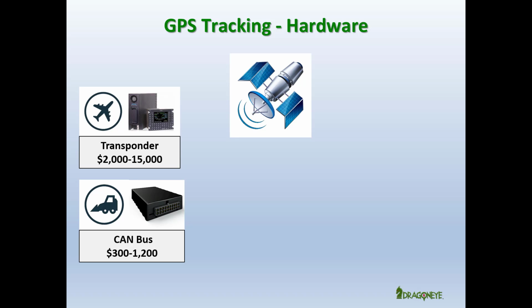Data coming in from other vehicle functions monitored by the vehicle's controller area network, CAN bus, such as plow height, lights on off, wipers on off, can also be used to update route driving conditions to a control center as frequently as every quarter mile.